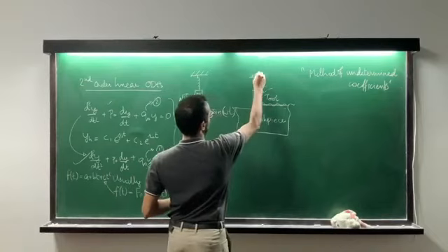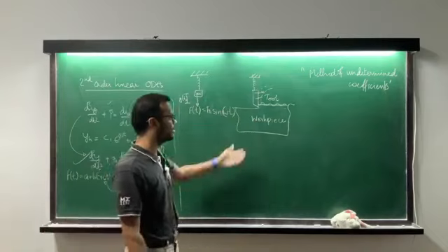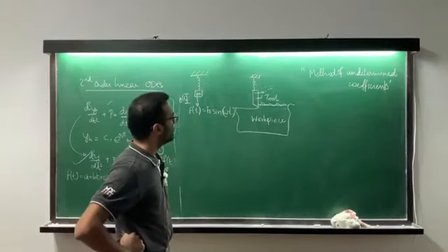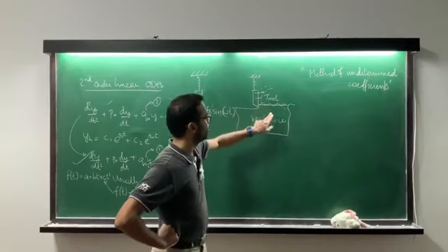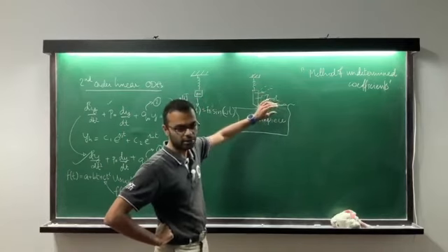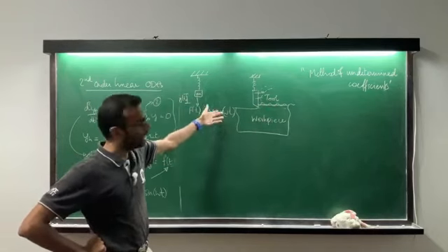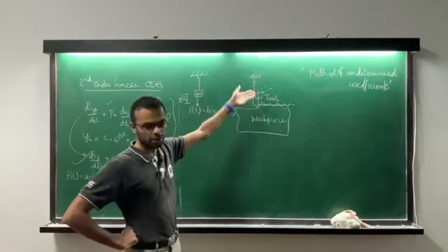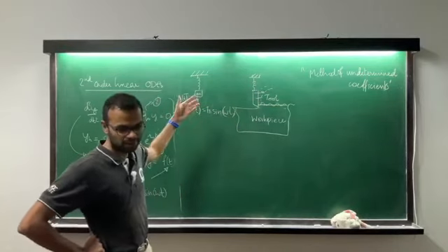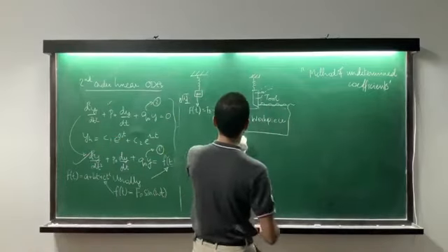The tool presumably also has some damping, but we will not worry about it for now because this makes things a little more complicated algebraically, but it's something I'm sure you can work out. If it has undulations, then because the force is proportional to the thickness, the force is undulating as a function of t, so the force is going to look something like this. And if you want to measure the deflection or the vibration in the tool, then you will be solving exactly this problem. So it looks like a trivial problem, but you can use it for something that is practically relevant.